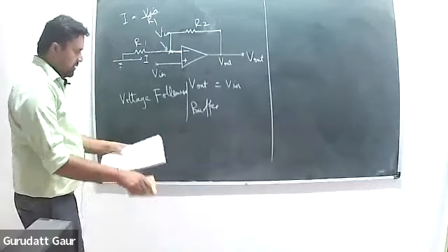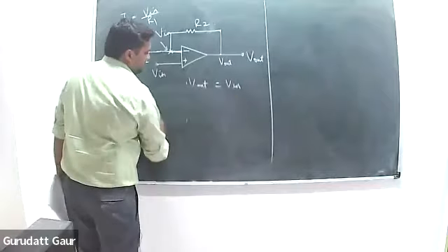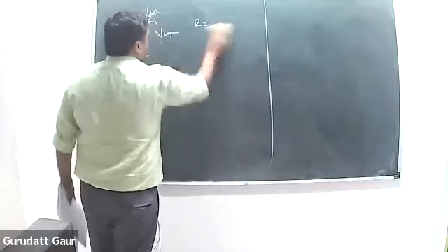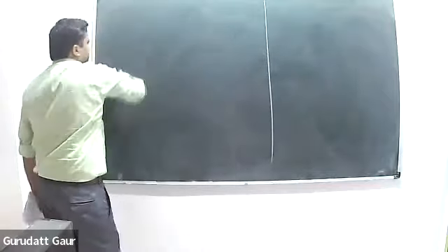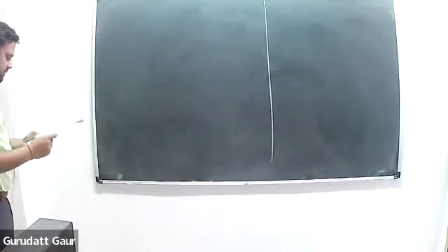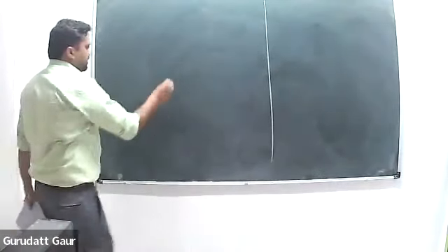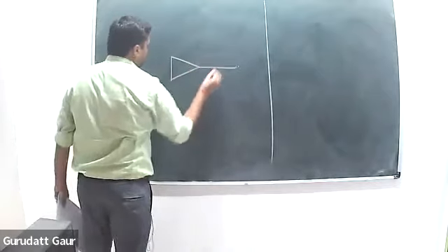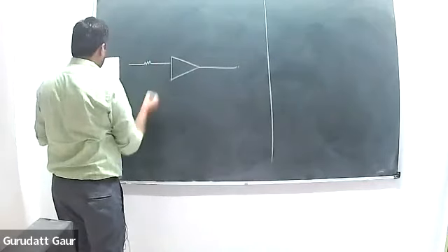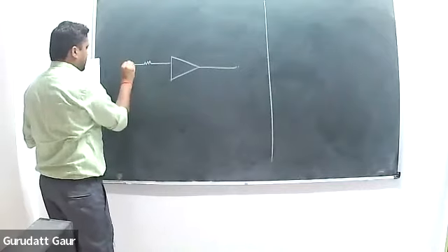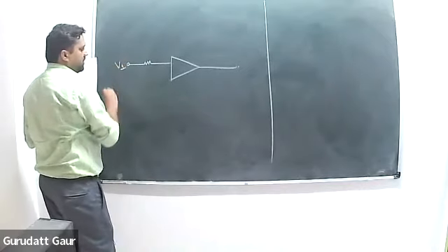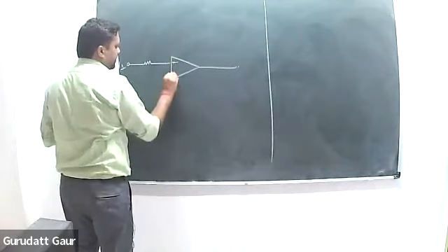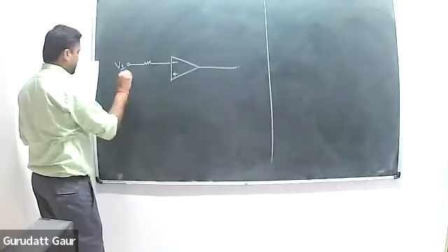All right. Differential amplifier, which is what this was initially made for. Now you want to amplify the difference of the two signals, so you will be applying the input to both the terminals. This is the output. You apply the voltage V1 through R1 to this terminal, and you want to apply the voltage V2 to this one also.